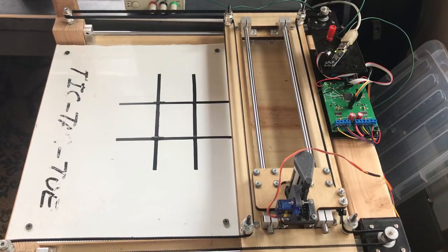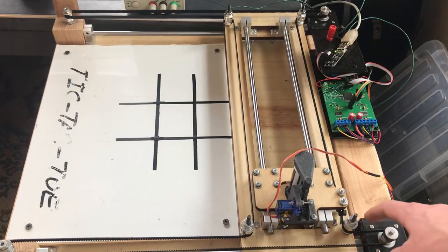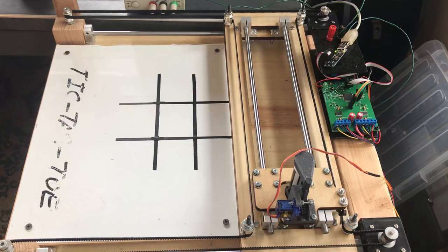though if you are to get them, I highly recommend you check each one for the quality of the ball bearings, as those seem to vary substantially. The pulleys that you see located here and the belt were bought straight off of Amazon. I believe this is 3mm wide GT2 2mm pitch belt. I can check on that.